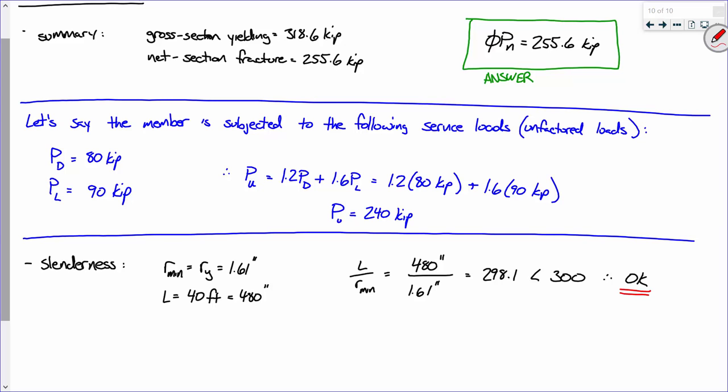I mean, let's say we're talking about tension members, okay? A very common place for tension members to go is either in a truss or in some bracing system for a building, right? I mean, you can't just sit it there and that's it. You have to connect it to the rest of the structure. Now, you could use welds, and if you used welds, yeah, you'd have a stronger net section capacity because you wouldn't be removing material due to the presence of bolts, because there's no bolts.